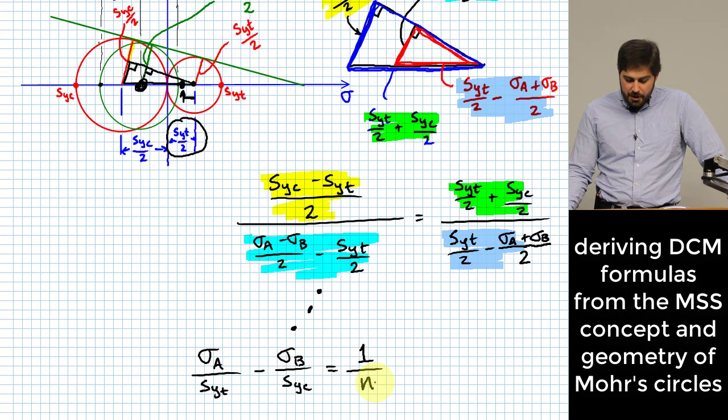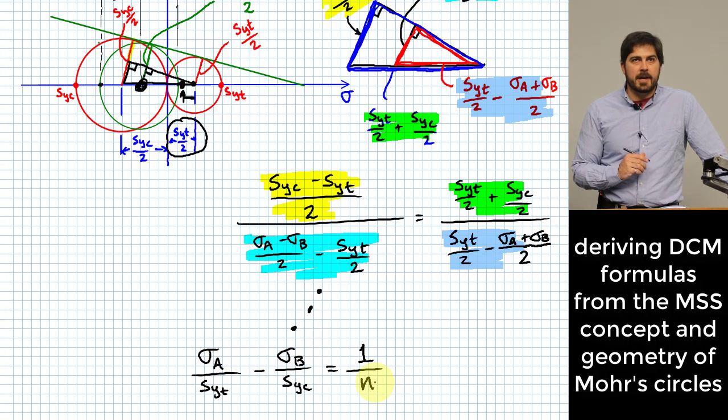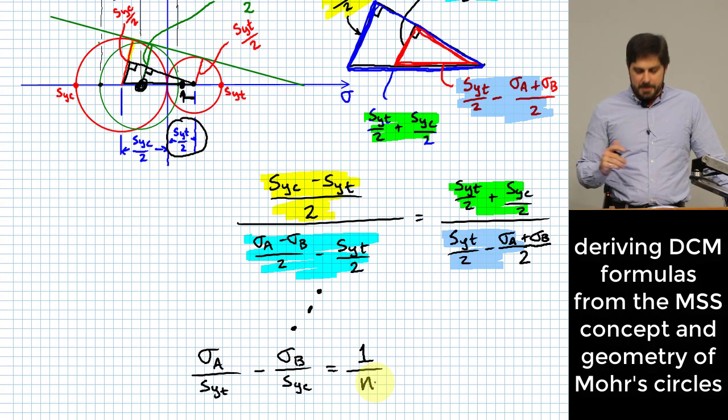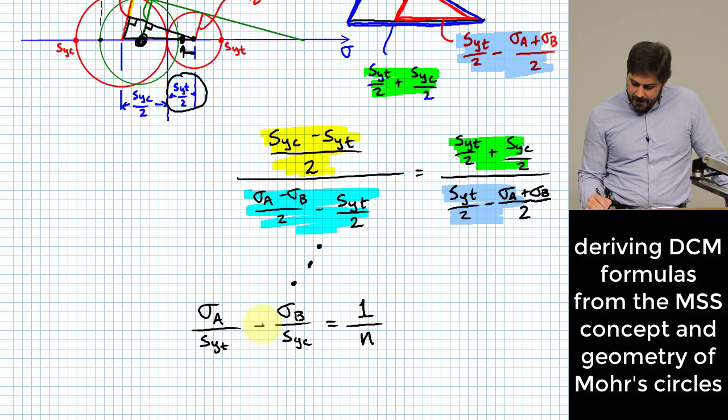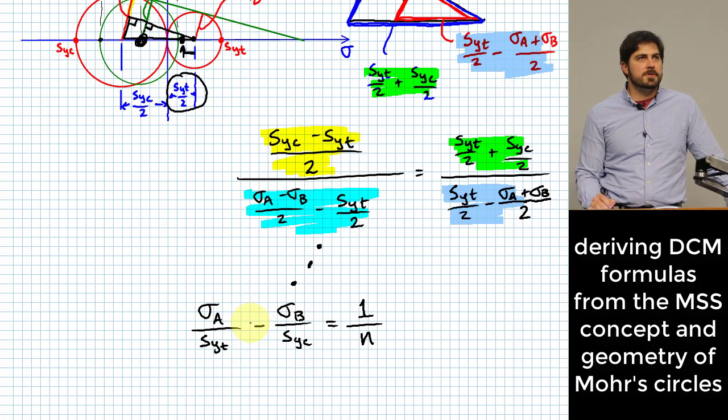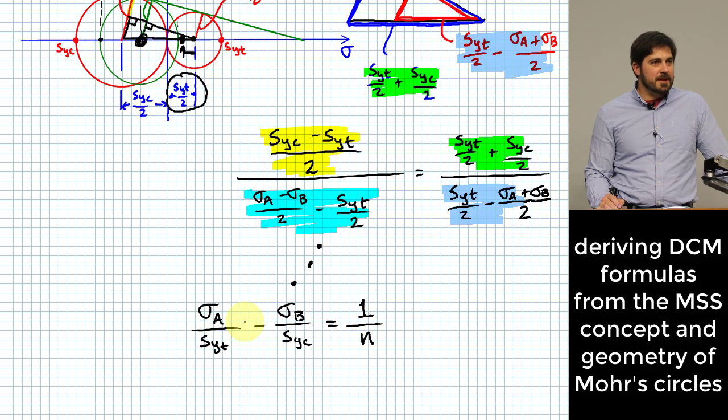You could also think about that in terms of strengths, right? If you wanted to make your part stronger, then you could use stronger materials. That would decrease the values that are in the denominator here, okay? And you'd achieve a similar idea with that factor of safety. All right, quick comment on this before we move ahead and do a problem. The comment I want to make is about this negative sign that we have right here. This is confusing for some folks, so I figured I'd talk about why we have this negative sign.